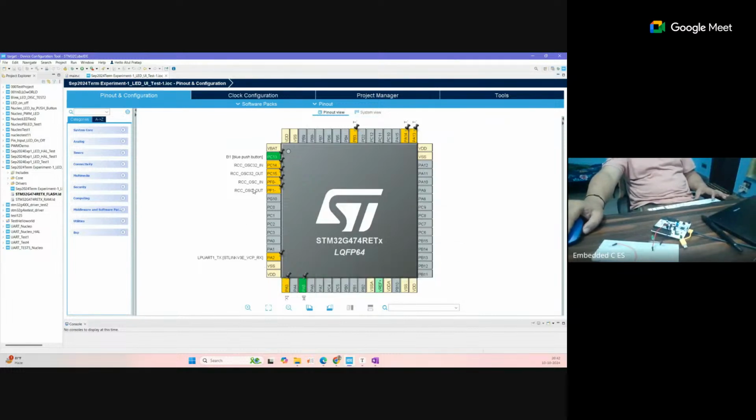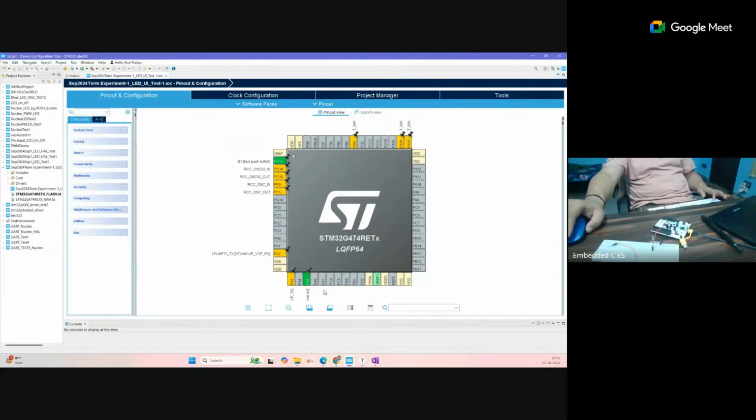to use this. So here you can see this PA5 is already available here, and this is green actually. Okay, so by default we can change the state for the reset state, or we can change it for some other purpose like GPIO input. Okay, so that becomes an input pin now. Okay, and now GPIO output, if we are making it, our purpose is GPIO output. Okay, so now we are using this pin as a GPIO output.